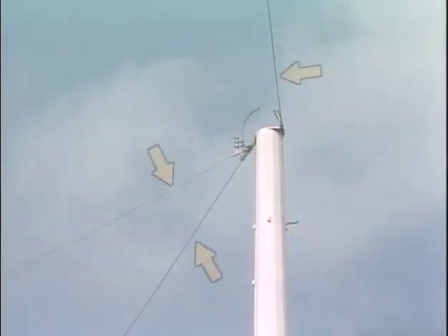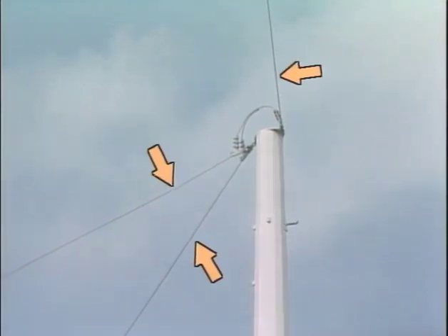Besides corona rings, another device called a static wire is connected to most structures. Static wires are used to dissipate the effects of lightning. They're tied directly to the tops of structures. Although static wires don't directly relate to power loss, they do prevent damage to transmission lines, which could otherwise lead to serious power loss. Static wires are strung overhead between structures, tying all structures together.